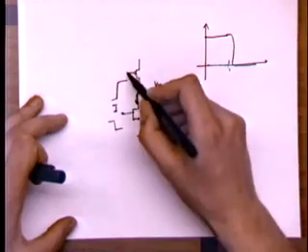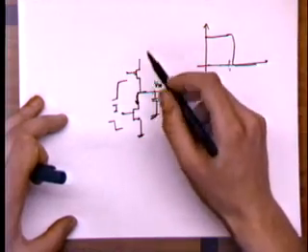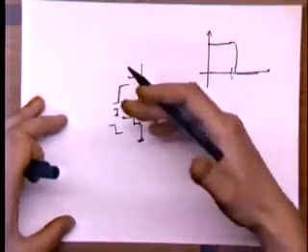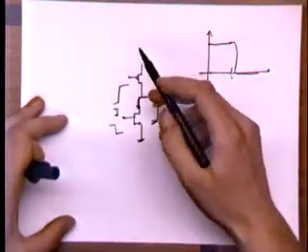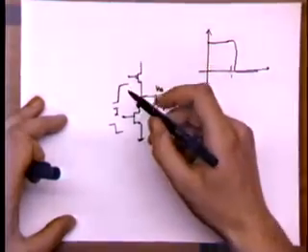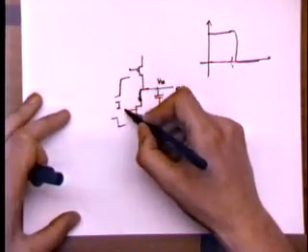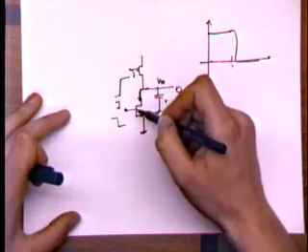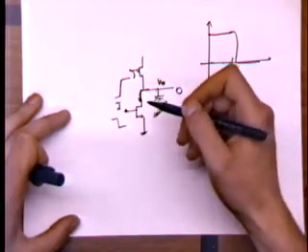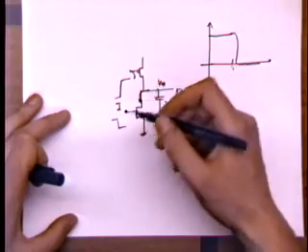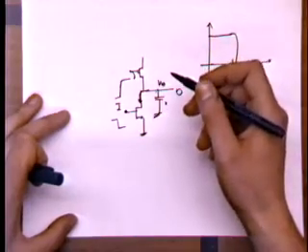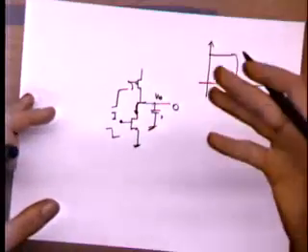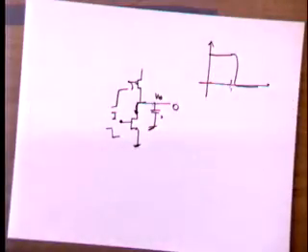And this is typically done with the PMOS. This is called a dynamic logic family, and you will see more about this in the next lectures. But this is typically done for speed, because you can see now, instead of having to enter on an N and a P, as in a CMOS gate, you are entering only on NMOS, okay? So your capacitance is lowered by, roughly speaking, a factor of 3. So because you have lower capacitance, you get basically higher speed for the same current, okay?